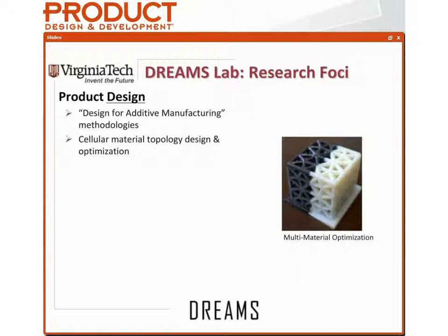I should mention that in that photo on the right, you'll actually see that half of that product is black and half of it's white. That's actually the Vero white, which is a very stiff polymer from the Objet Connex, and the black is actually this Tango Black material, which is elastic, almost elastomeric. So what we've done is we actually not only have a complete complex geometry, but we actually have modified its material properties on the fly. So as a designer, I not only can specify where the material is, exactly where I need it, but I can also start specifying exactly the material properties where I need them, which is something that we as designers have never had the opportunity to do before.